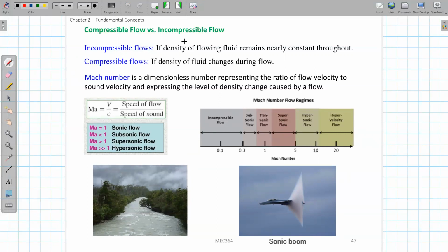Usually when we talk about incompressible and compressible, we are focusing on gas, because for liquid, usually you won't be able to change the density too much. You cannot compress liquid too much, right? But for gas, we can compress it a lot. If I compress the gas and reduce the volume, its pressure and density will increase, from the thermodynamics class we took before, that piston cylinder configuration we mentioned.